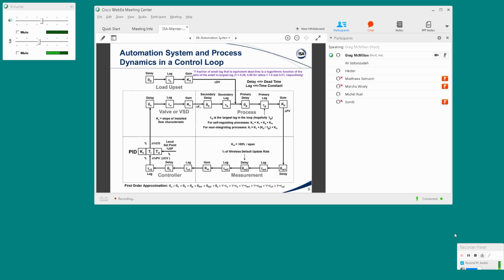And then there can be situations where there's both a large dead time and a large secondary lag. So what I did was modify my lambda equations to take into account both the secondary lag and the dead time in terms of the rate action. This keeps you out of trouble in that if you don't have much of a secondary lag or you haven't identified it, you still get the rate action you need. It just makes more sense to me to resolve this difference that's out there, with people saying this tuning method is much better than another tuning method, and they come up with a case. Really, you can probably modify most tuning methods to deal with these cases, and you should also realize there are other cases.